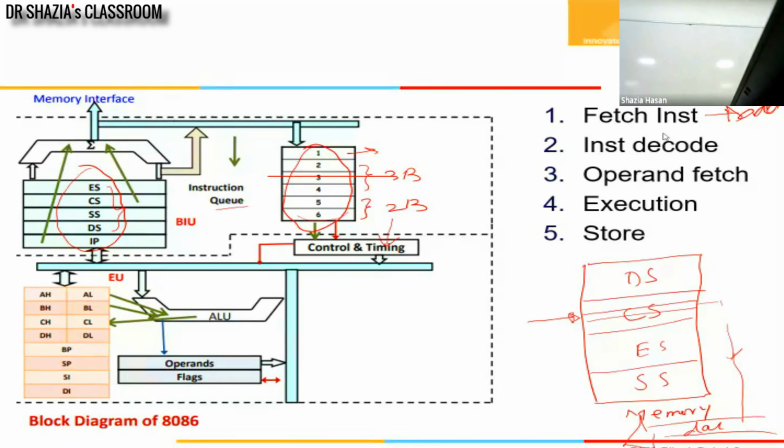So that address again will be sent through the address generator. We will go to that specific address in the data segment, fetch the data operand and make it available to your ALU. And then in your ALU, those data will be stored into the temporary registers. Here we have a set of temporary registers.